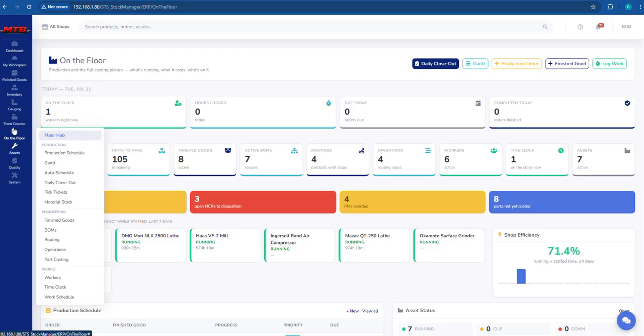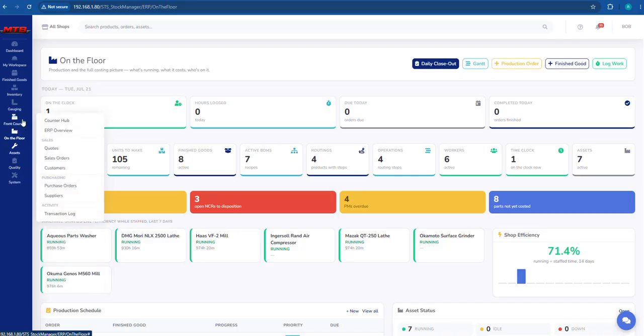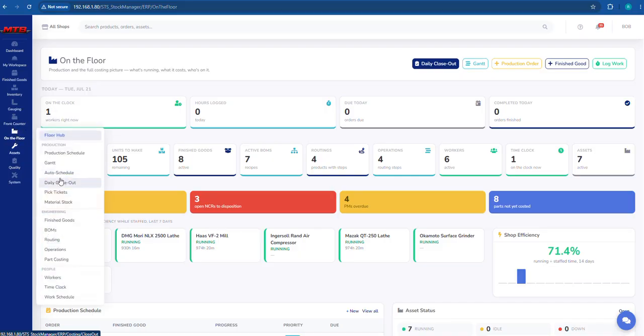like walk up to a machine for a setup, hit play, it'll tell you how long you hit play, stop, it'll record the time of the setup, then hit play again to run off your first part, hit stop, and then hit play again to inspect your first part, and then hit stop, and you actually get your setup time, you actually get your first part runoff time and your inspection time, which should be what you set as your baseline for your manufacturer time. And then you can kind of oversee and see if you're achieving that as your guys log in the amount of parts per day that they make. So it's some simple math, right? So that's kind of a neat feature as well.